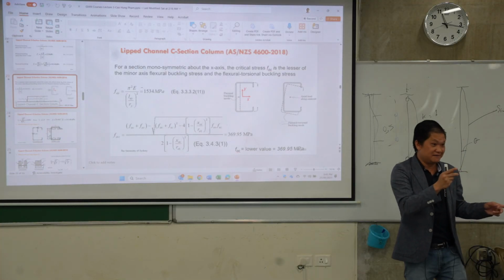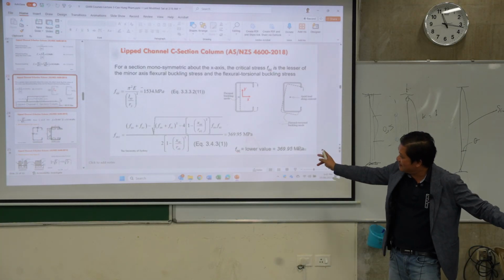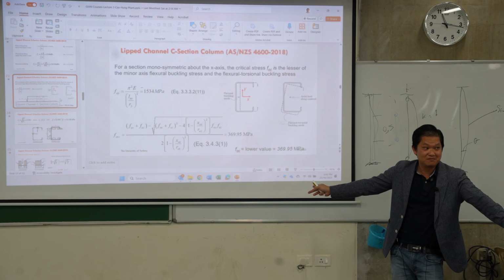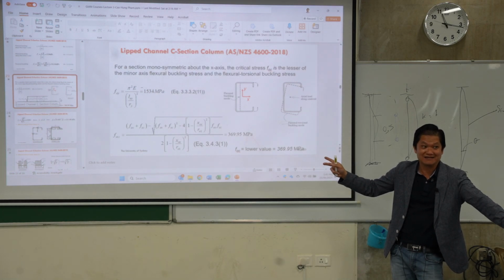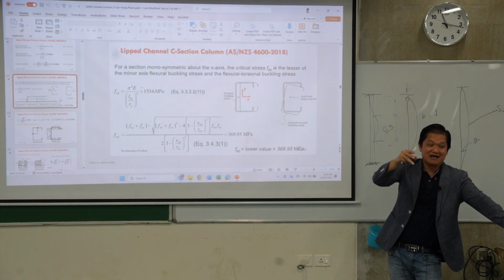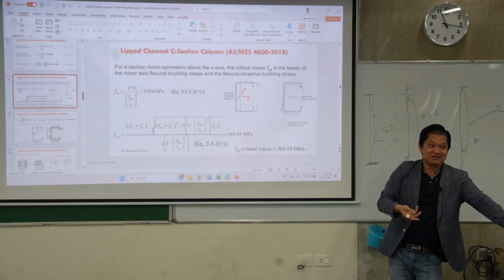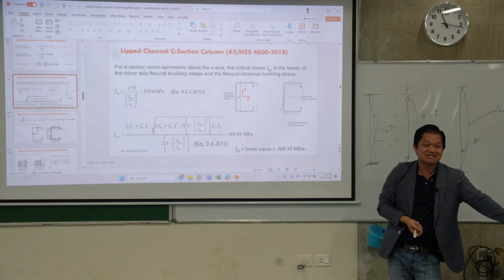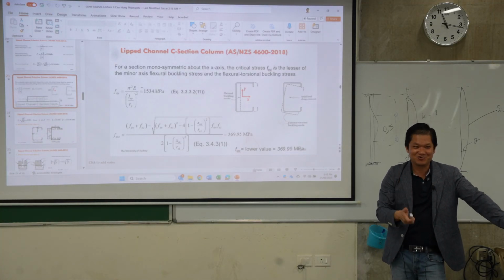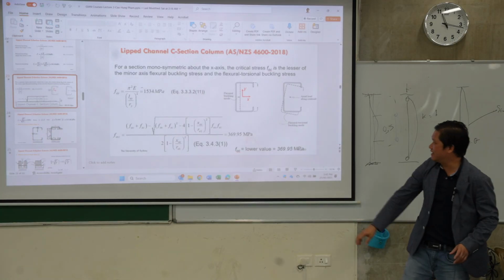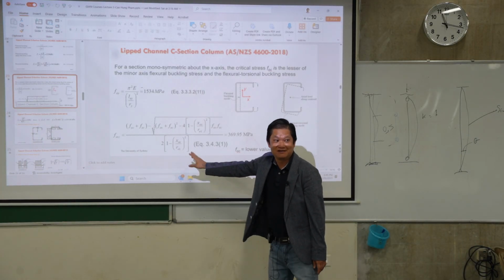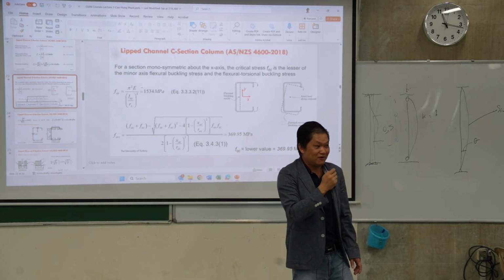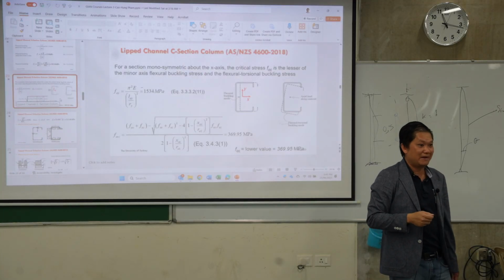But remember, you asked a very good question. So this is actually from Thin-Wall 2, but it's buckling, not strength. Then you have to use the lambda, and then you have to use that to get to that one. That's right. But you can save a lot of time. Just get it directly from Thin-Wall. It gives you the whole member capacity.